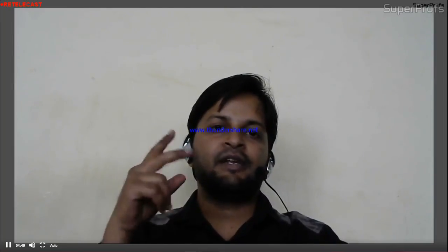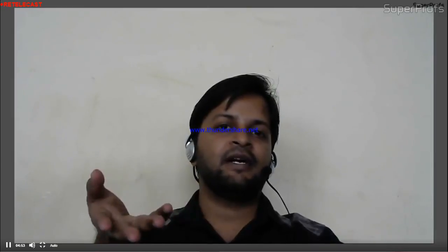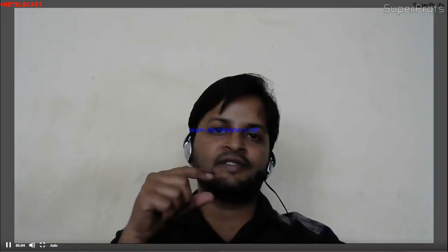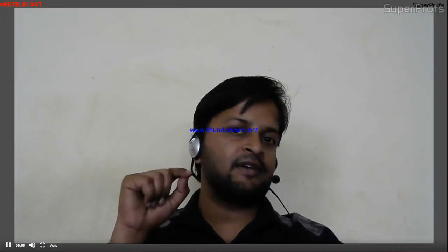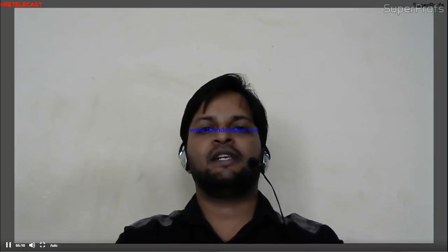Now by some method we'll calculate V by I, and tell me what is the V by I? V by I is nothing but the resistance appearing across the terminal. Is it? The current sucked by this network is nothing but V by R equivalent. So this is the procedure to find the R equivalent. I hope it's clear to you.